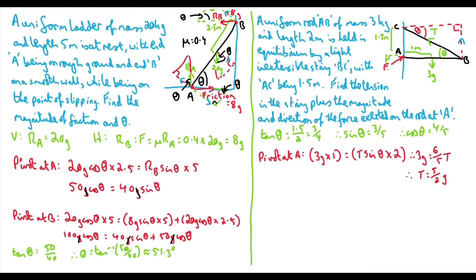So the angle we're probably going to measure is this here because it's the angle at A, but we don't know what that angle is going to be. We don't know necessarily how it's going to relate to this angle here, theta, because as I say, we don't know which way this force is coming from. So we may want to label it as just something else. I'm going to label it as X. Okay. So now we are going to be able to take equilibrium in the horizontal and the vertical.